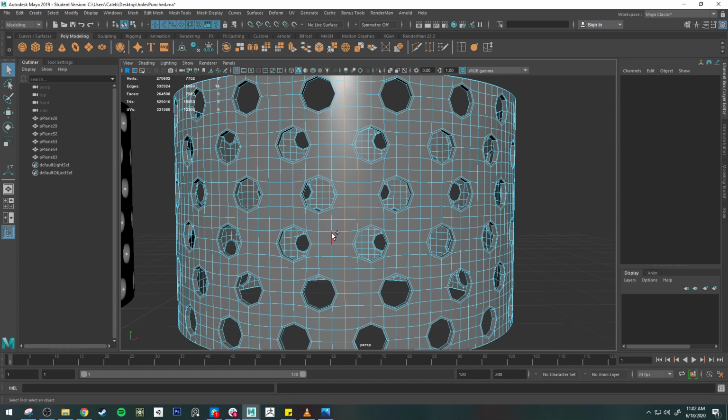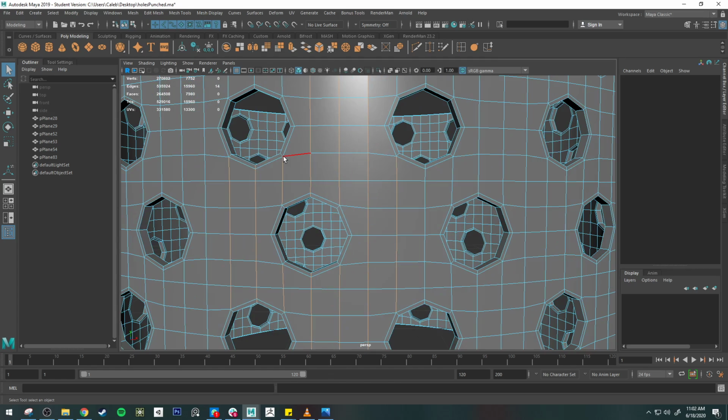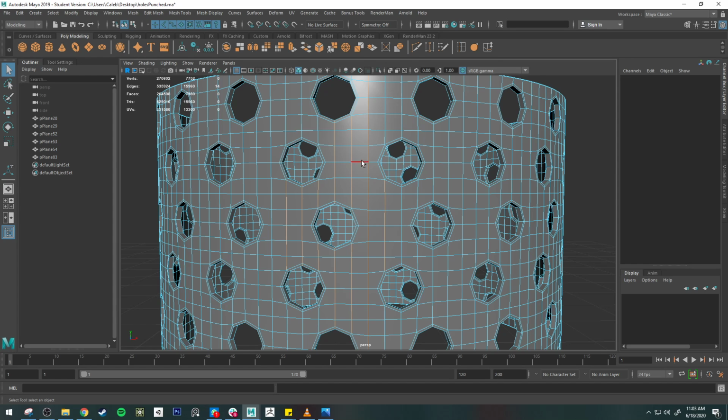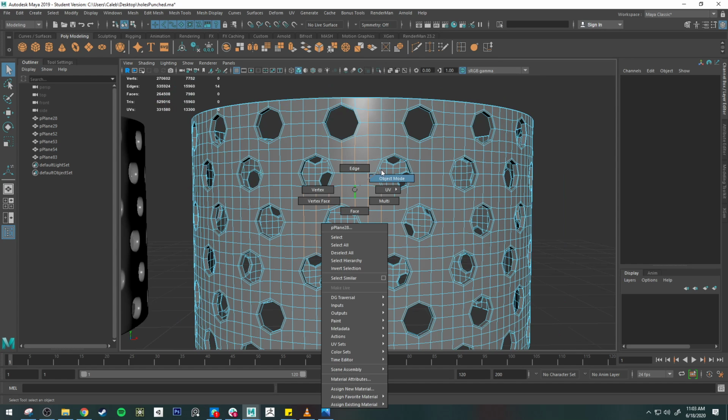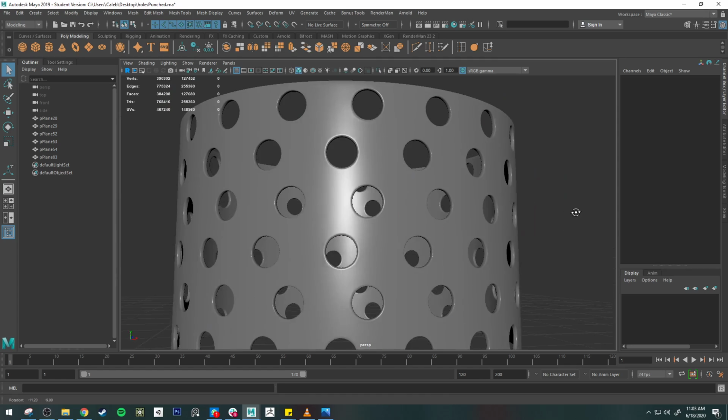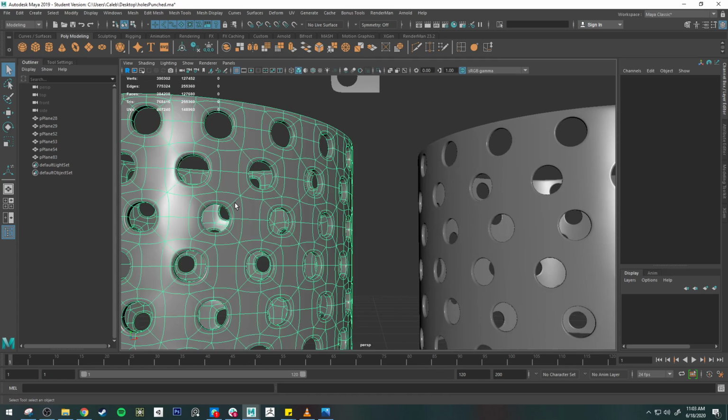more or less linear and evenly spaced in this direction, as you can see here, you see these edges are pretty much evenly spaced from each other. They're almost straight. There's very little pooling. There are poles, but they're very, very tight right here, and there's an edge between them, so it's keeping it from pooling. You see these poles right here? They're not getting pulled too far, so these edges are staying pretty straight. And that's what gives this one a fairly smooth surface compared to this one.